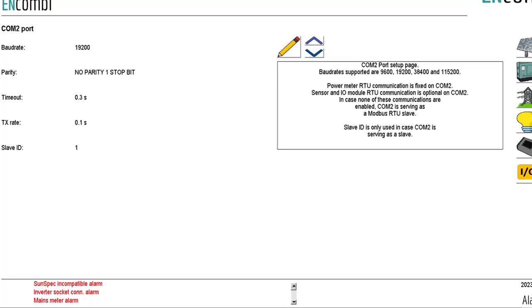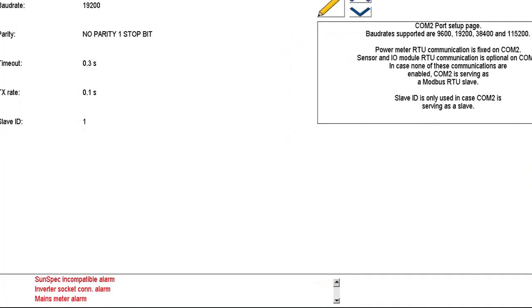Please note, not all the alarms are customization alarms, which means some alarms act as a kind of communication fail notification on your site installation. This kind of alarm will be self-erased once you rectify the issues. For example, the common meter communication alarm or sensor alarm.